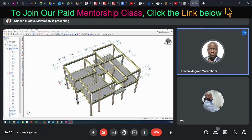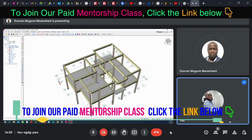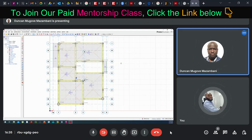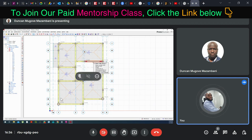Okay. So go back to your plan view, story one. Click on story one and make it active. That's fine. Now click on one of the beams and let's input our wall load, where I will show you how we got that 9.81 for our cantilever loads.